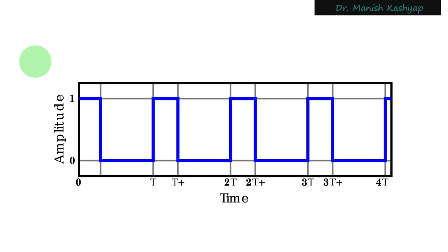Now, let us talk about the structure of the clock that we have in the 8086 microprocessor. Obviously, you have to use a pulse in the clock circuit, and the kind of pulse that we are using in this 8086 microprocessor is very specific. It has to be a pulse which is on for 33% of the time, and for the rest of the time it is off. That means alternatively we can say that we need a pulse whose duty cycle is 33%. All of you might be aware of this terminology.